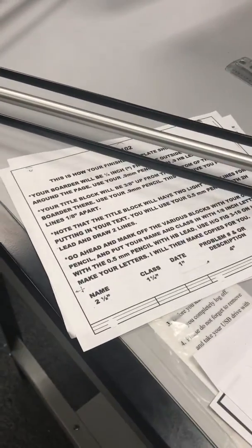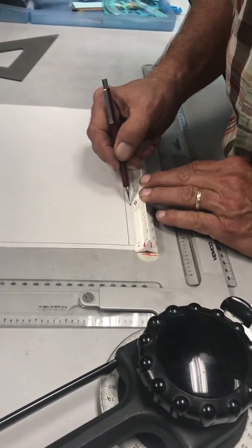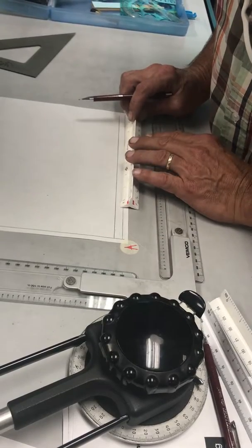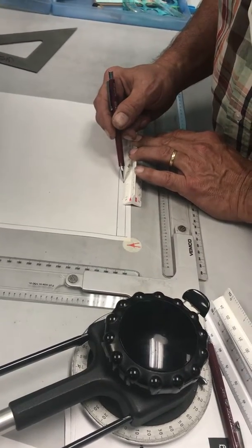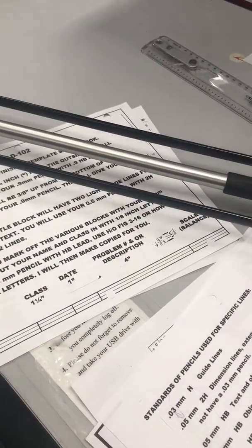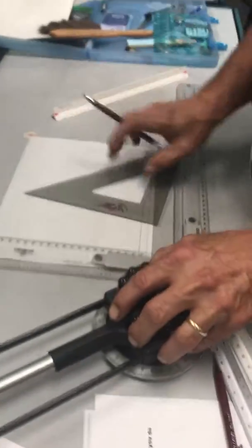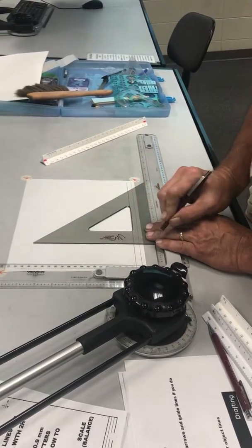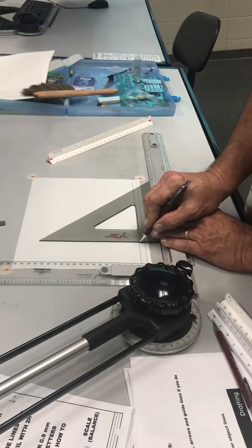Now each one of these, this is 2.5 inches away. So what I'm going to do, I'm going to take this down, I'm going to find 2.5, which is right here. I'm going to go ahead and mark these all out. Next one is 1.25 inches. So we can either do the math, or I can just bring this back over to where I stopped for my 2.5 and do 1.25 inches. And I'm going to continue on till I get all of these right, and then I'm either going to use this or I'm going to use my triangle. I like to use my triangle. So I'm not going to push it, I'm going to pull back.